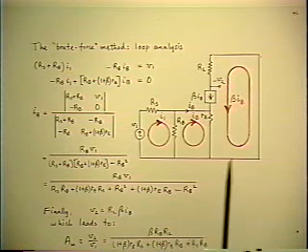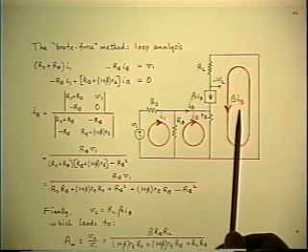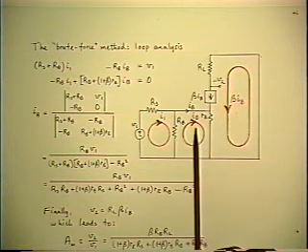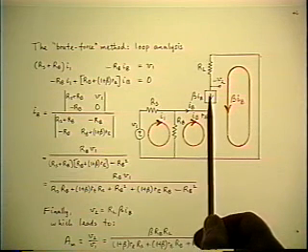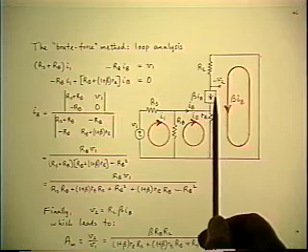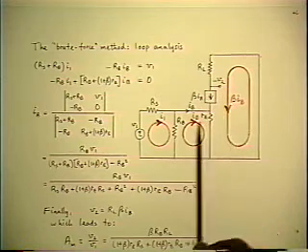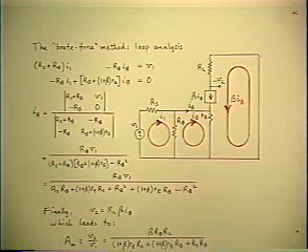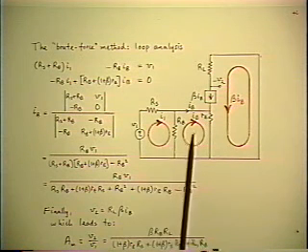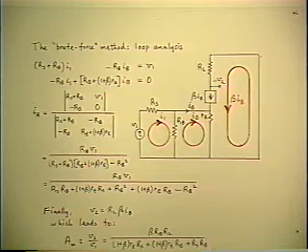The problem in this case is actually a little simpler, because the third loop current is a fixed multiple of the second one because of the properties of the equivalent circuit model in this particular example, because the third loop current is beta times the second loop current. So already this is simplified down to only a 2 independent loop current model.